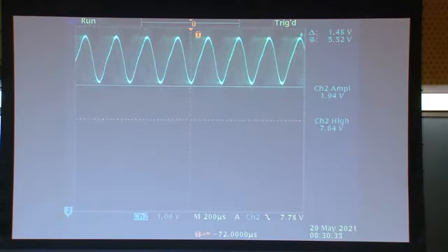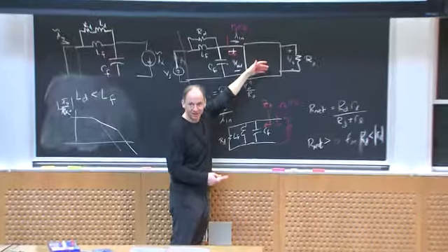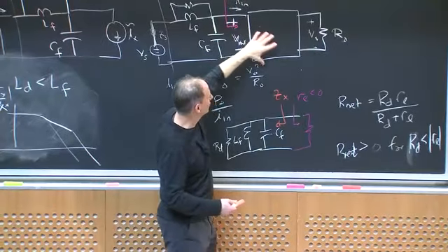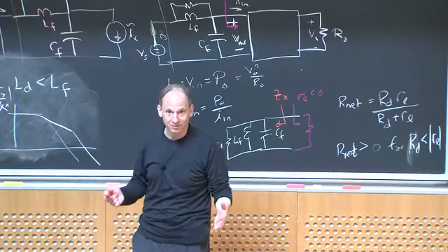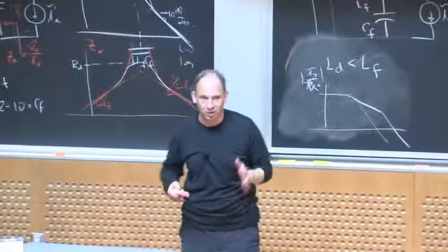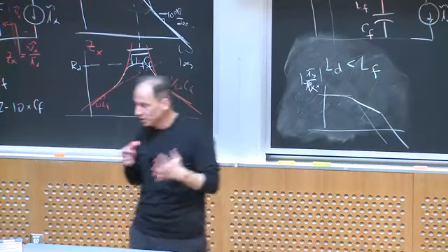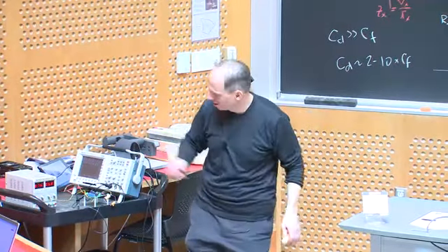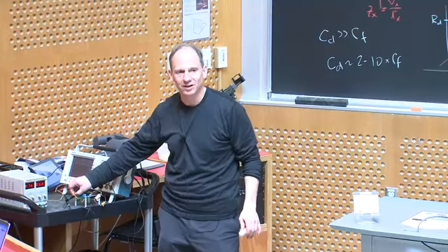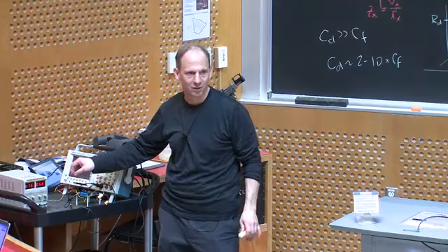You say, well, I can live with that. I don't care. Well, it depends, right? Sometimes you hear a lot of noise. This is just with the converter at some value of load. But imagine this thing were trying to draw current varying near that frequency. It would go really crazy, right? So you really can't tolerate this kind of thing. And you would see this in the converter response at the output and so forth. So you really do have to seriously account not only for the fact that you need a damped LC, but you need to account for the negative input impedance of the converter in order to get acceptable response. Any question about that?